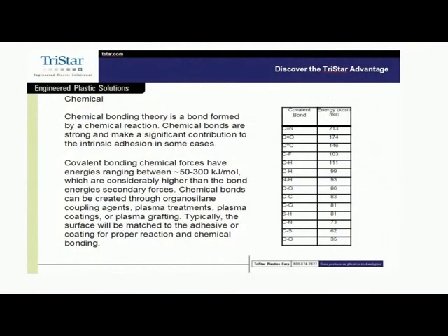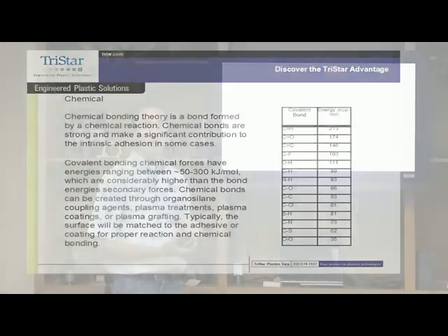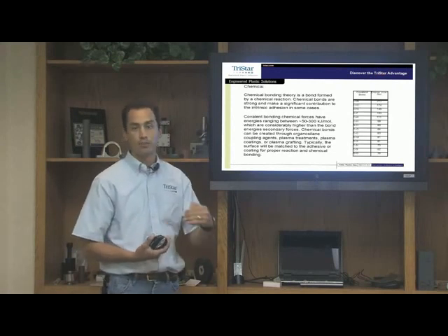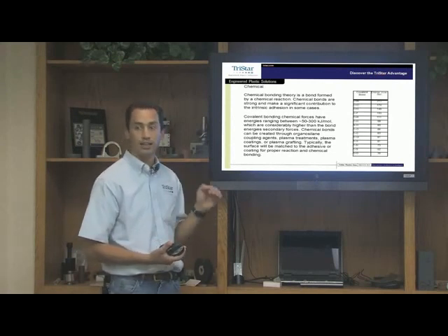Chemical attachment is really where we start to hang our hat. That's where we're exploiting our newest technologies with organosilane deposition and molecular grafting. The previous slide showed wettability, and along with wettability comes chemical activity. You could refer to this as molecular Velcro, in that these compounds are actually locking together. They're actually reacting. And this bond strength is many times stronger than hydrogen bonding. So even though we can exploit hydrogen bonding, we can further that point and advance technology by reacting surfaces together.